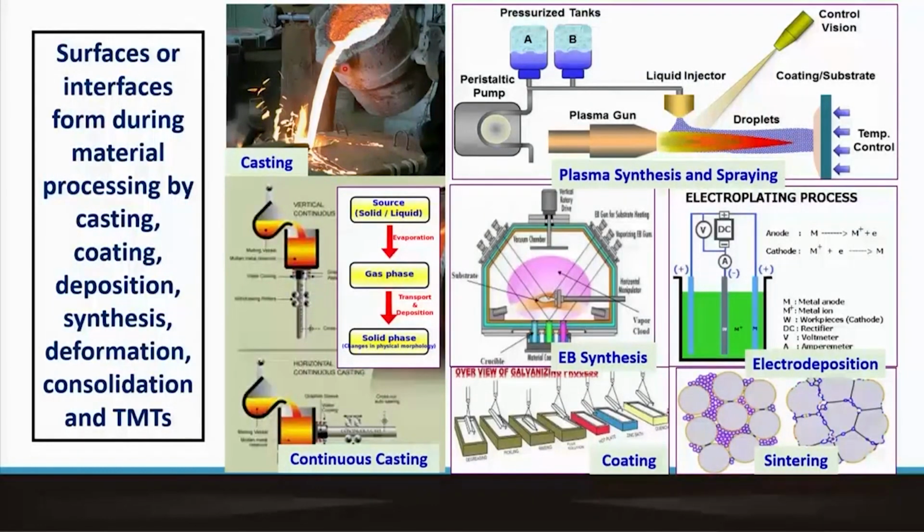Say, for example, the same liquid metal may be poured into a tundish, and from that you carry the hot metal through various rolls and various configurations of casting rolls. And instead of producing a semi-finished product like an ingot or a starting material, you actually can form thin sheets or wires or rods and coil them up, by virtue of which it can be ready for shipping to the destination.